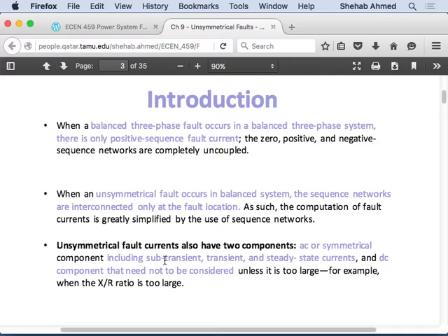If your fault current is 1,000 or 10,000 amps, there will be a force on the bus bars inside your cabinets, inside your substations, that you have to account for. That's why the subtransient impedance is an important consideration. So you will typically use the subtransient impedance in your fault calculations when you are trying to select the circuit breaker's peak current. The circuit breaker has a short circuit capability.